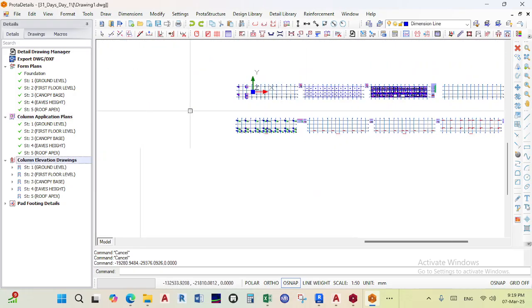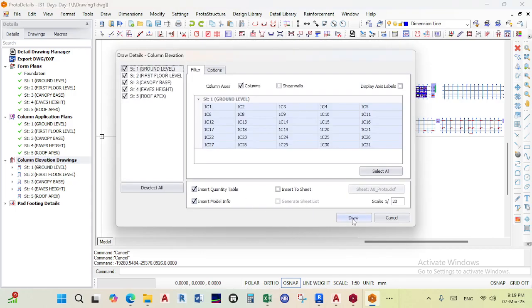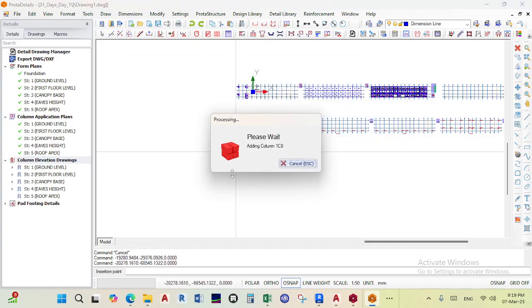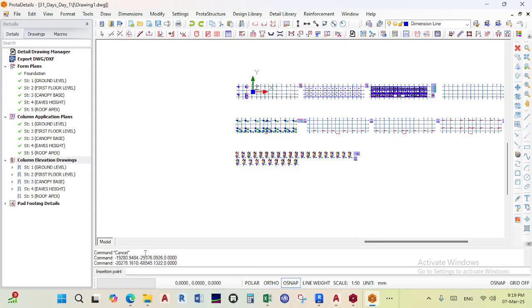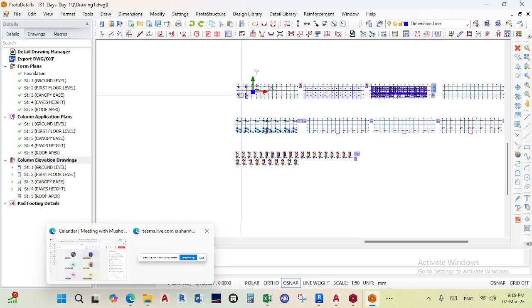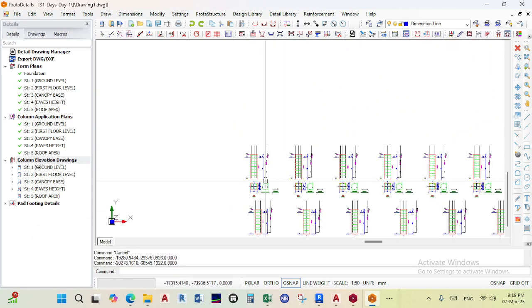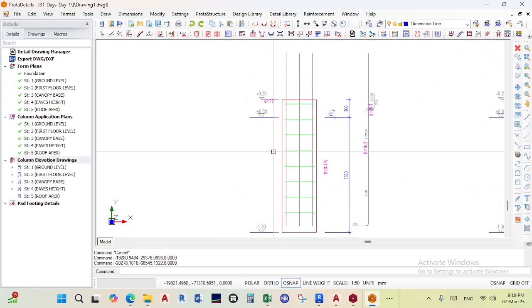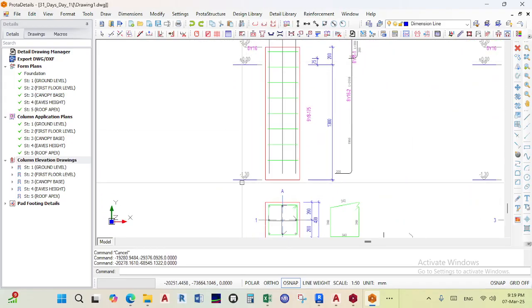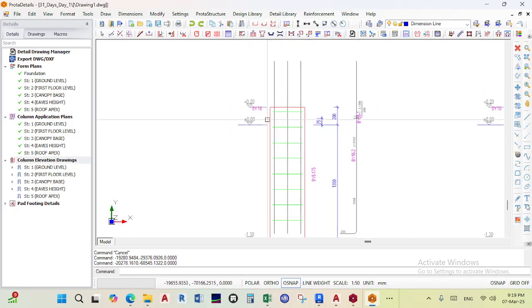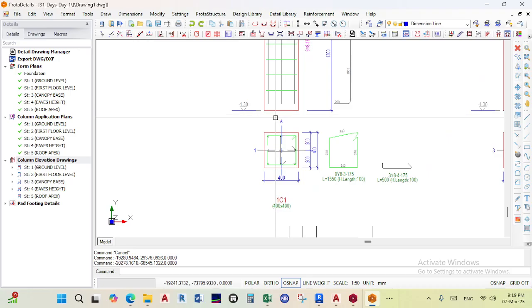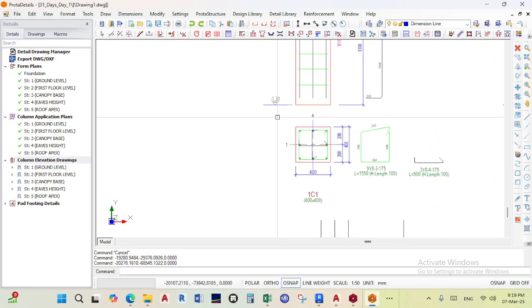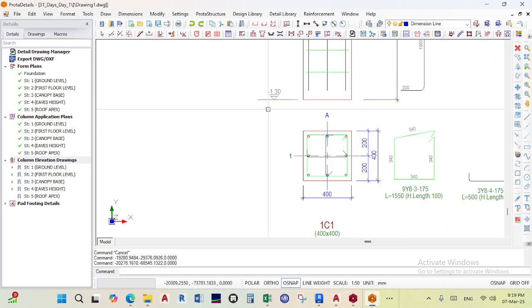Oh, column elevations are here. These are sections. So let me right click there, draw column elevations. It's going to look like this. Aha, it will give you the depths. Here it tells us that it goes from 0 up until 1.3. This is your stub length before creating that 200 step. And then depending on how you designed your footings, you would add the thickness of the footing.